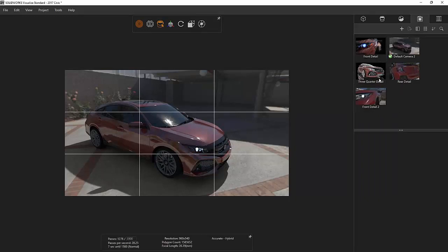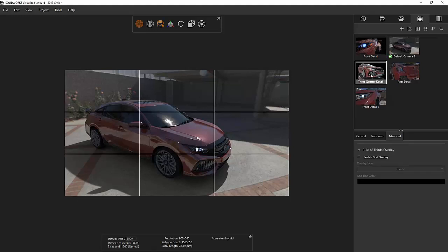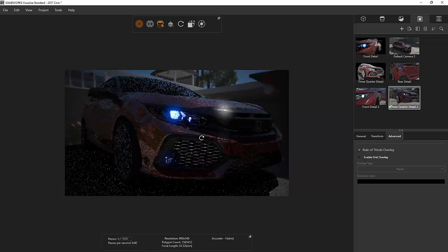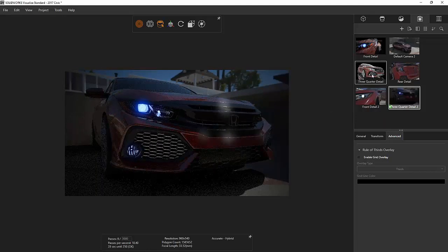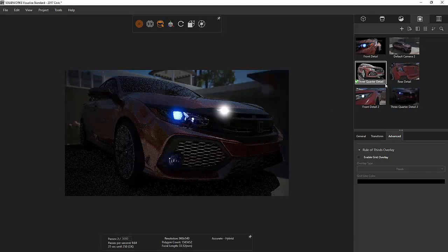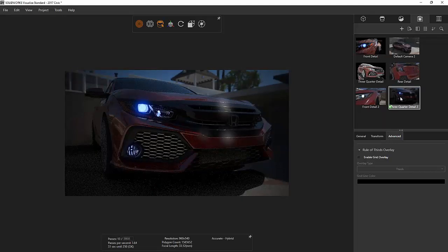The other one you can do is if you want the same camera, don't copy and paste it. Hit the Control D key. So I'm going to pick this camera, hit Control D, and we can see that we have another one that was automatically generated here. So once again, kind of nice, especially if you want to just tweak that view a little bit. I can come in here and now I can tweak that a little bit, and it didn't ruin the first one. In fact, all I did was capture another version. You're not going to make your file size that much bigger by doing this. This is very small pieces of information here. So not copying the whole model, just a secondary camera. So don't be afraid to use those. Definitely a good way to get them to work better for you.